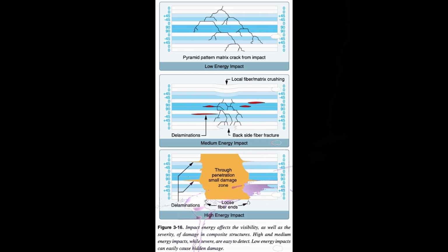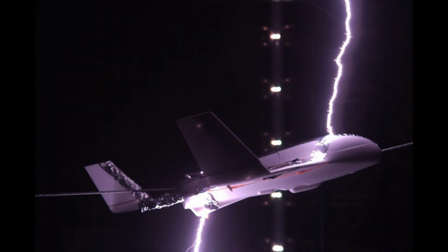Lightning strike protection. Lightning strike protection is an important consideration in aircraft design. When an aircraft is hit by lightning, a very large amount of energy is delivered to the structure. Whether flying a light general aviation (GA) aircraft or a large airliner, the basic principle of lightning strike protection is the same. For any size aircraft, the energy from the strike must be spread over a large surface area to lower the amps per square inch to a harmless level.